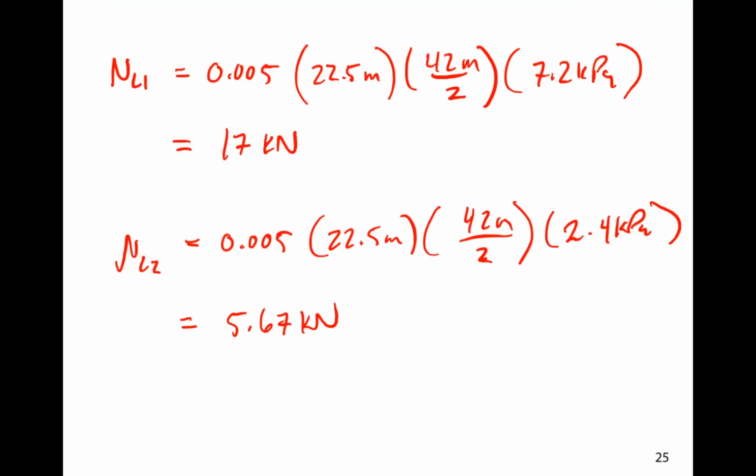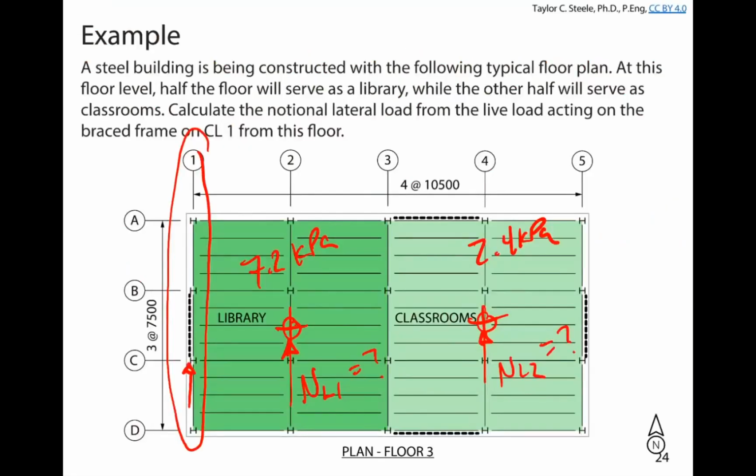In fact, the building code doesn't tell us much about how we should apply a live load reduction factor for this case, and neither does F16. The answer is the lateral load effects are going to be affecting braces, for example. And if we go back to the idea that tributary area is the floor space that the element is responsible for supporting load from, then the braced frame at the left-hand side here, if this was uniform distributed office space, that braced frame is going to see office live load from half of the floor level at 3 floors.